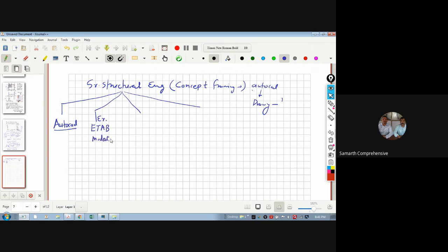He is modeling, then putting the gravity loads and earthquake loads. He is doing the analysis, then checking the results and so on. So ETABS modeling is done. Then there is a design team. In the design team, either RCDC software is used or Excel sheets are used. He can use any method. He will design the members: design of column, design of slabs, and so on.